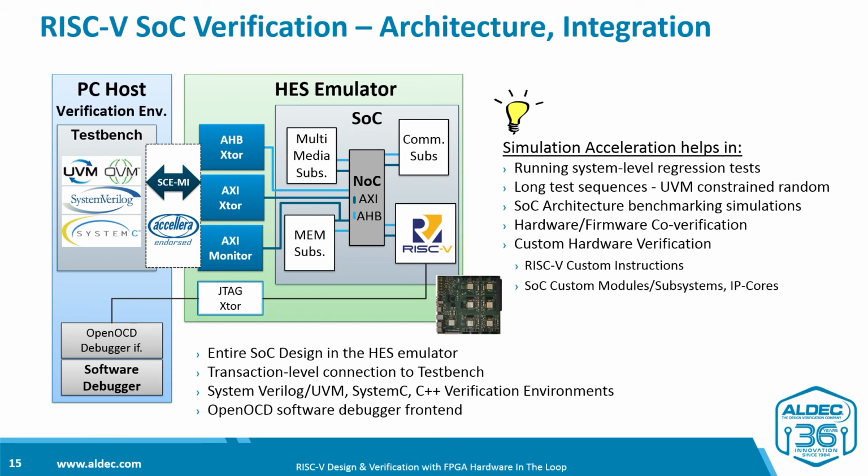Let's take another example of emulation, which is the case of integrating an entire SoC and performing system-level verification. Now, the emulation can be used either by a hardware team or by a software team. The hardware team can use emulation to verify system-level integrity and requirements, as well as run regression tests after each update committed by developers. In this case, the idea of using or reusing the system-level test bench for simulation and emulation is the same as before at RISC-V core level verification.